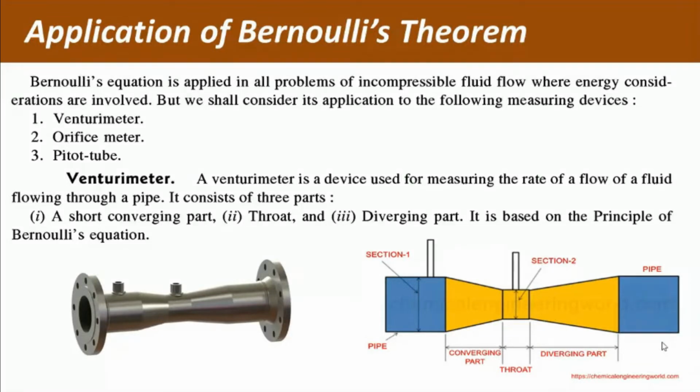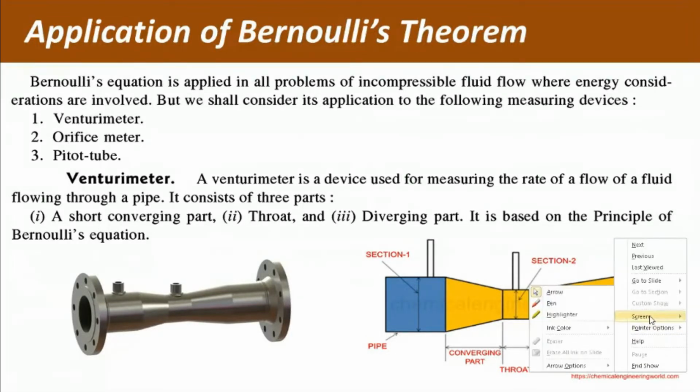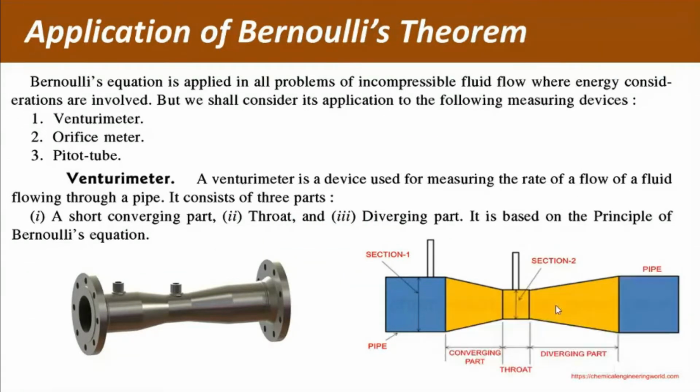So Venturi meter basically consists of 5 sections. First section is inlet section. In the inlet section, you can see there is a constant diameter pipe section. Its diameter is equal to whatever the diameter of pipe where Venturi meter is to be connected. Here one pressure tapping is provided in the inlet section. So this is inlet section.